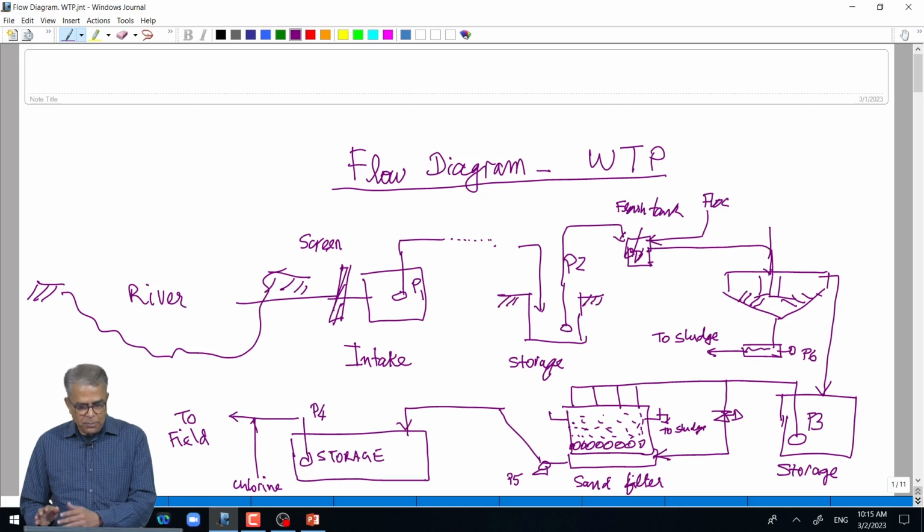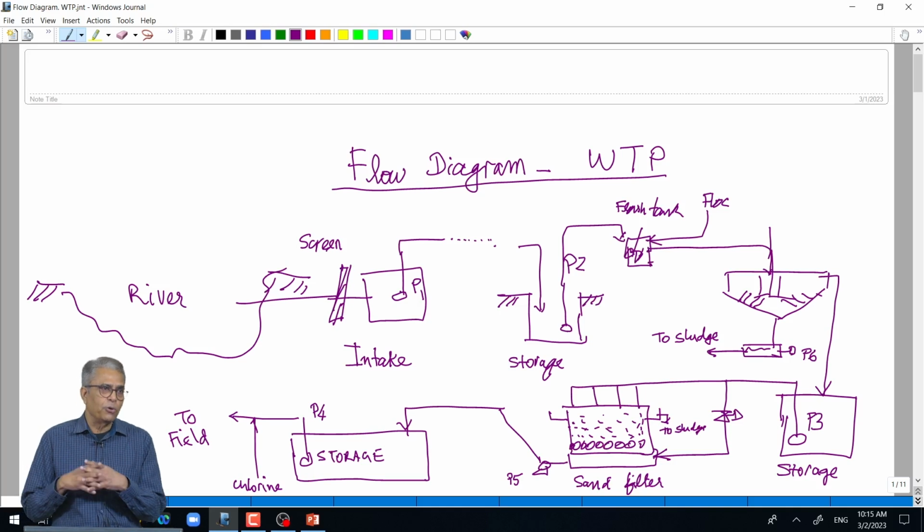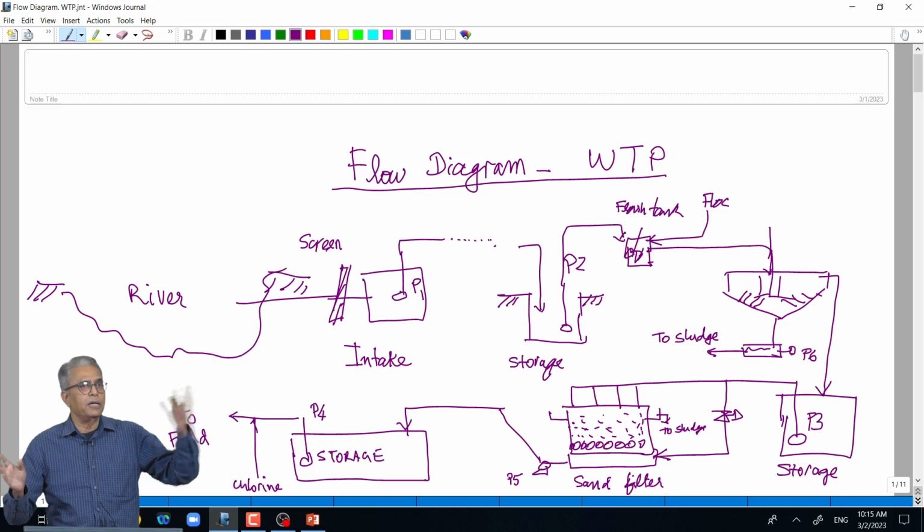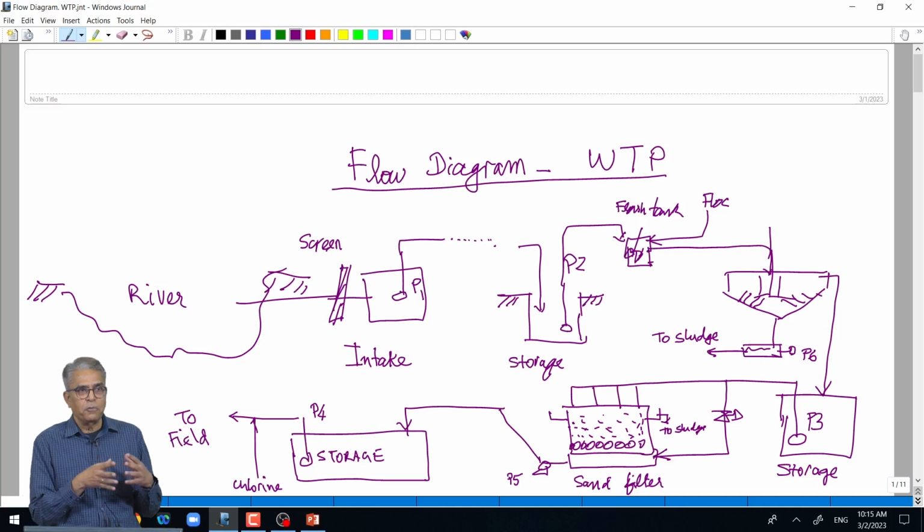Then the water treatment plant, you will usually locate it closest to the point of consumption. The reason being the pipeline, because after you make the water it has to be reaching all the guys who need it. So, if they are all distributed in this street, that street, etc., if your water treatment plant is very close by, then the piping requirements will be less, and this is not one massive piping you can put and get away, streets, tapping here, lots of complications.